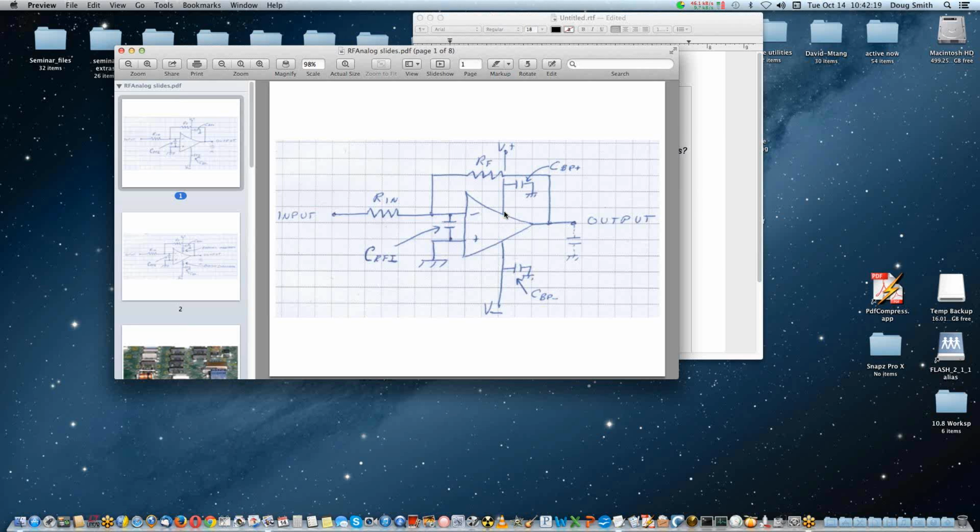But if you do that, you've got to make sure they let you know of any changes to their process, or do a little test every once in a while. Build up a test jig that's sort of like your own circuit, maybe right over a ground plane to keep RF conditions constant, and then feed in a controlled amount of RF and see how sensitive it is, with direct connections, like through an SMA connector or something, and then characterize it, and then once in a while check incoming and make sure that they haven't changed a lot.